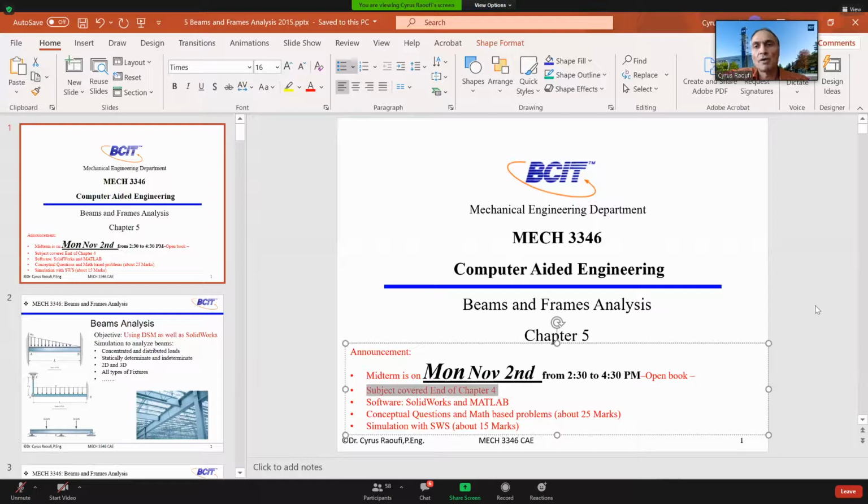That was approach 1. Approach 2, we said in SolidWorks simulation, you are going to start from weldment, and you are going to make the part with weldment. If you do that, then when you go to the SolidWorks simulation environment, again, you have a multi-body environment, but this time you do not have to convert or treat them as a beam. Automatically, SolidWorks simulation is going to consider weldment as a beam element by default. And we said that is a one-directional beam element, and then we talked about the direct stiffness method.